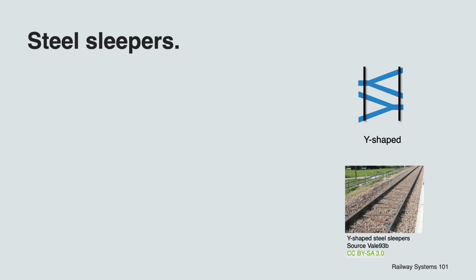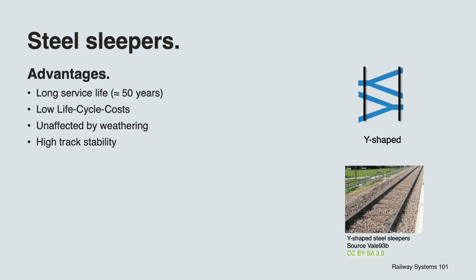Usually, their main benefits are reduced costs of production in difficult locations, as their lower required footprint reduces the logistical needs at the construction site, for example by less excavation material needing to be displaced, and a substructure and ballast layer that can be lighter and thinner. Y-sleepers can be laid on ballasted bed and on slab track.